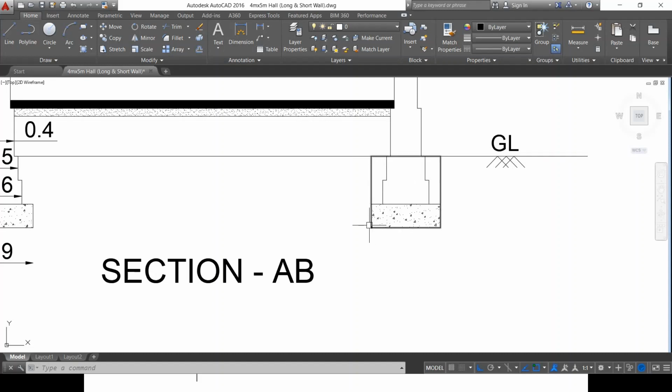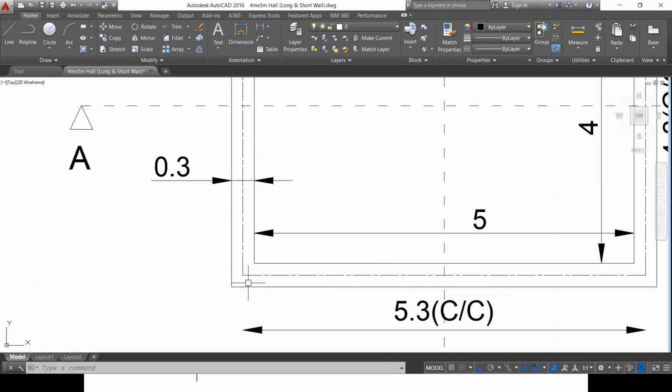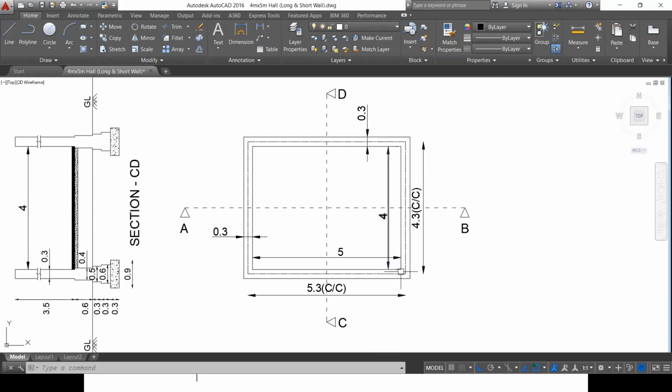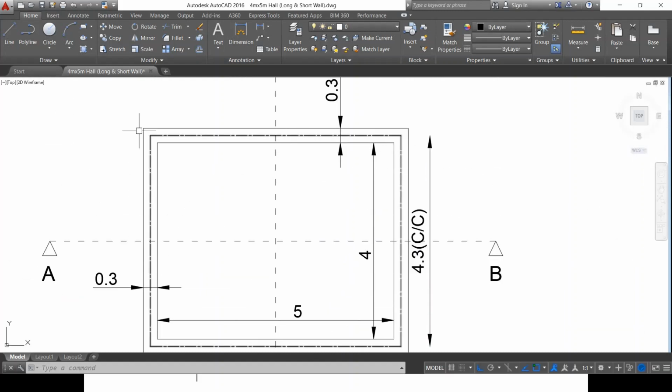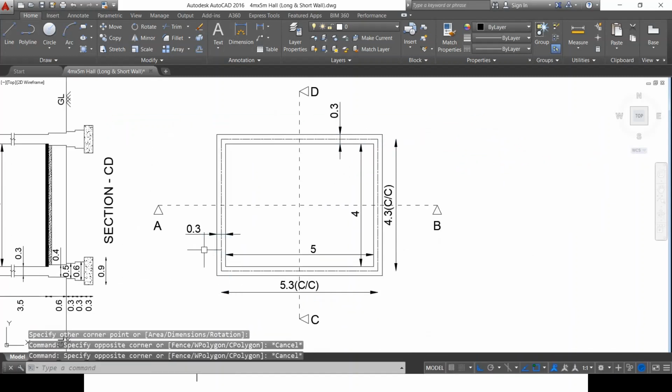So in order to do this earthwork in excavation, the first thing I have to determine is the length, which is nothing but the length of the wall along which I have to do the excavation. Here I have 4 walls. Along the length of the wall I have to do the excavation. So starting from here till here, and from here to here, and from here to here, and finally from here to here. All the 4 sides have to be excavated. So that will be my length.